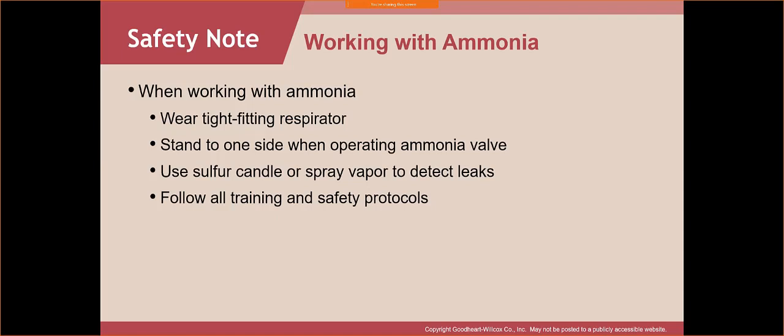So if you walked into a store or an industrial sector, and let's just say their condenser is in a small little room, and it's leaking, you're not going to smell it because most refrigerants are odorless. You walk into the space, you may suffocate because the refrigerant has displaced the air and you die. So if you walk into these smaller rooms, it's nice to have a little personal monitor that's going to detect the refrigerant. Sometimes they even have alarms in the different spaces to identify when the refrigerant leaks, which is also nice.